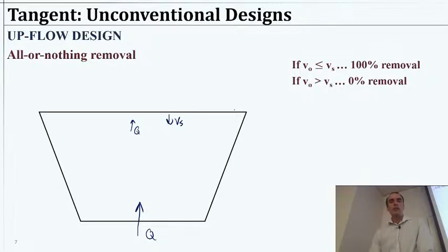As you're collecting water over the top, that's your effluent, so to speak, you'll have some design velocity: your settling has to be equal to the velocity of water going over. So this would be your V naught, that threshold of how quickly water is being pushed over the top. As long as you're under that, your particle should eventually settle.